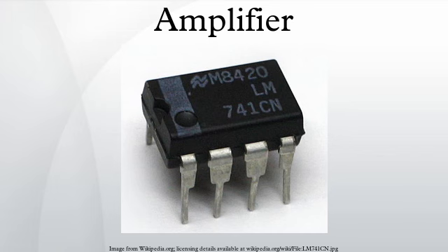A nonlinear amplifier in an analog computer or true RMS converter, for example, can provide a special transfer function, such as logarithmic or square law. A Class C RF amplifier may be chosen because it can be very efficient, but will be nonlinear. Following such an amplifier with a tank-tuned circuit can reduce unwanted harmonics sufficiently to be useful in transmitters, or some desired harmonic may be selected by setting the resonant frequency of the tuned circuit to a higher frequency rather than the fundamental frequency in frequency multiplier circuits.